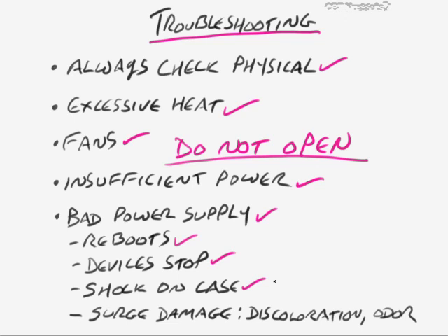It could be that a power cable has gotten pinched when you close the door. It might have gotten pinched on there, and so every time you touch the case, it sends a surge. This could also adversely affect various ports as well. So if current is traveling through that case, it could affect those ports like USB ports and FireWire as well. Look for signs of surge damage, which may have occurred. This will often occur as discoloration, especially around certain chips on the motherboard, for example. You might see some scoring or some discoloration.